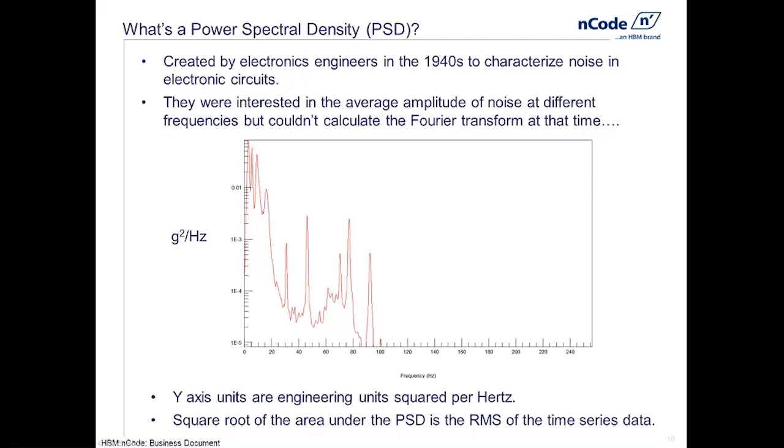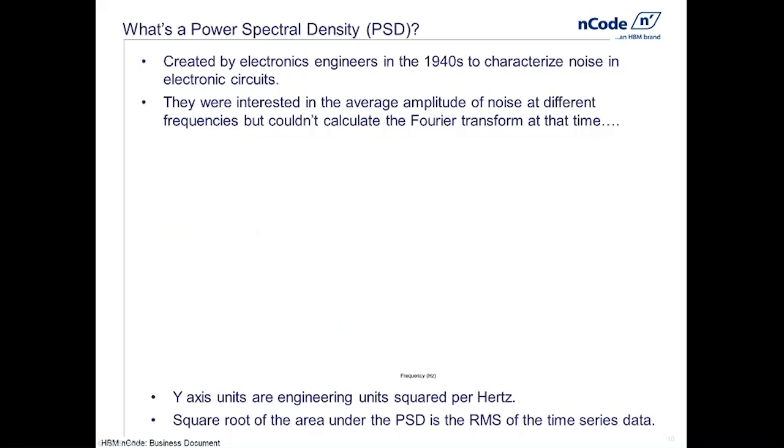So we can learn a lot by looking at things in the frequency domain. We can learn a lot by looking at things in the time domain. One point to make is that these amplitudes seen in this plot represent, for example at 40 hertz, where there's a peak at 40 or 45 hertz, the average amplitude of a 40 hertz sine wave running through the time series data. So the key point here is that it represents an average amplitude, or average power, running through the time series. Average is the key word here. It's going to come back and make us think a little bit about the loading data and whether we should be representing it with averages or not. So let's investigate that right now.